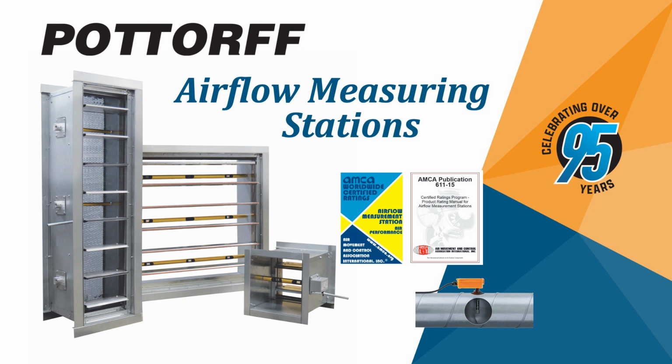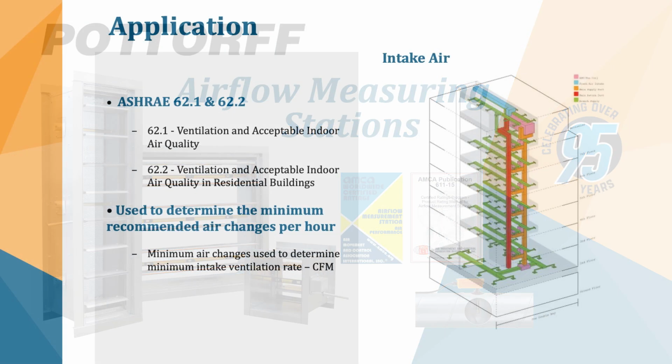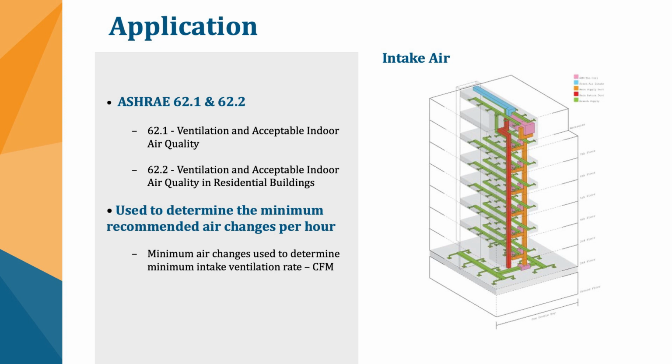While airflow measurement is a little less of our focus, we have a pretty strong line of dampers and louvers, but we have noticed the need for some airflow measurement equipment, and some airflow measurement equipment tied to dampers, where there's an adjustable control damper that can be positioned by the building management system based on, say, intake airflow requirements and things like that.